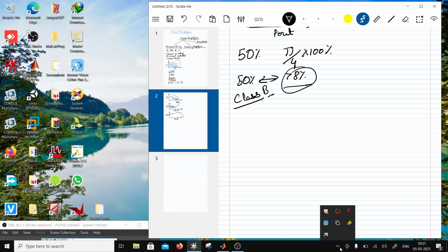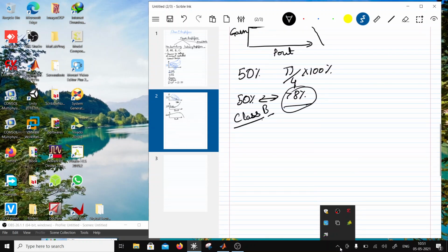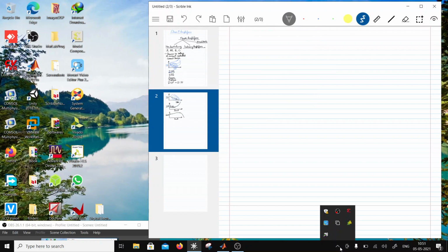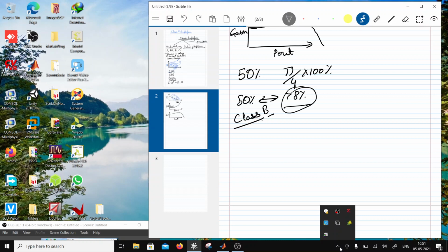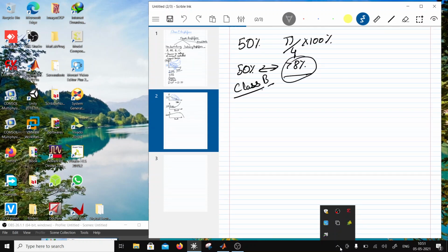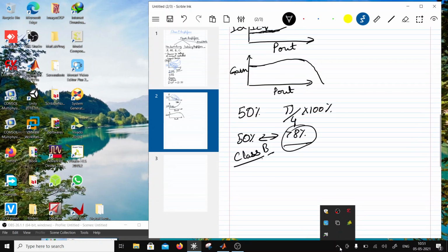You can derive this from the active region. So you are going to have pi by 4 times, because this is almost half wave rectified, right? If it is half wave rectified, the RMS value is going to be half, right? And when you multiply the two, there is a factor of 4. So that's the efficiency you're going to get. So this is a class B amplifier.